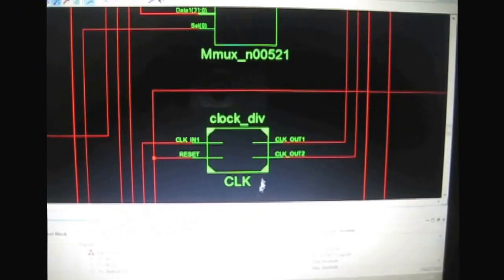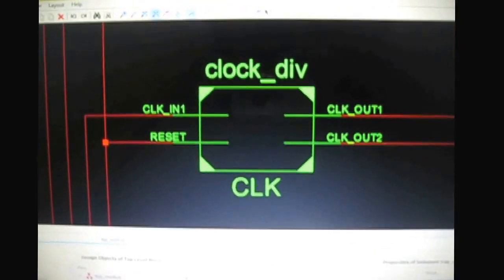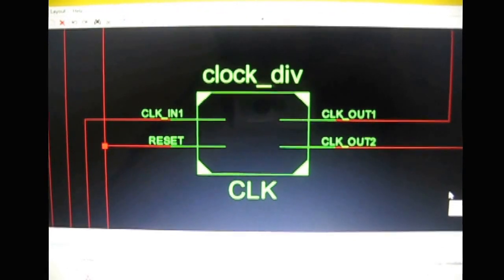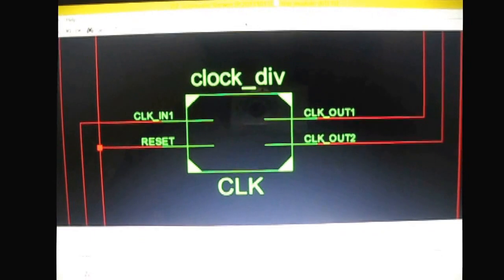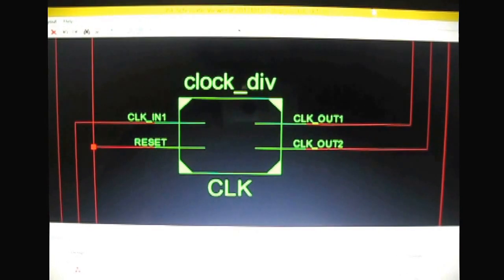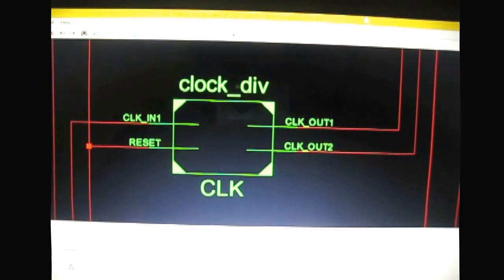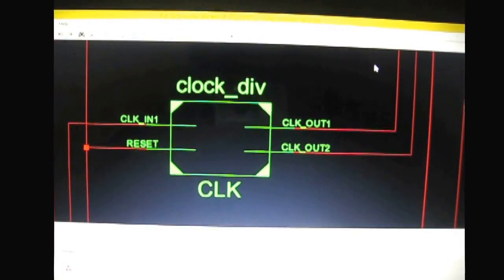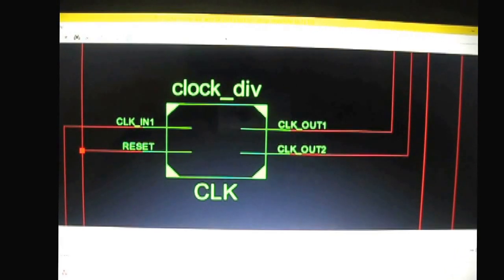And here you can see the clock div module. This was used, as I said just now, to divide the internal clock of our board so that it could meet our needs in terms of frequency, of course, since a regular SD screen has a 60 Hz refresh rate, and the PS2 keyboard exploits a 10 kHz internal clock to communicate with the external world.